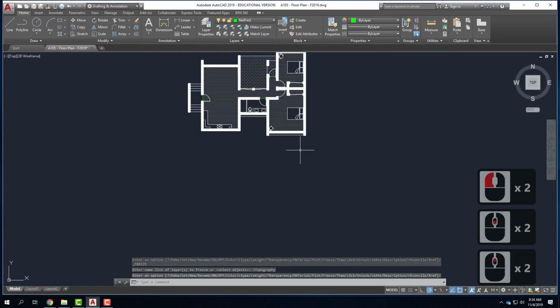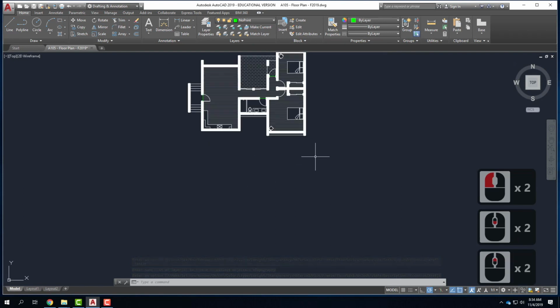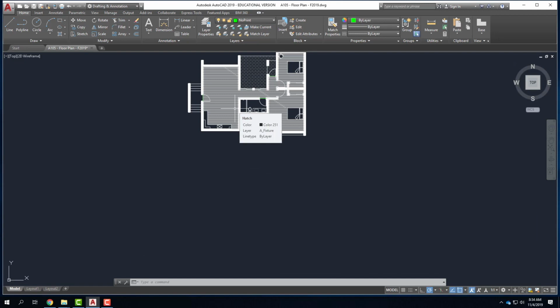There it is. We'll go ahead and turn that one off just so that it doesn't distract you while you're working on it. And I'm going to use my building's plan as a general guide as I lay out this particular building. So I need some guidelines or construction lines that I would pull down from the corners of this building, there, and there, to give myself an idea of what the shape of the building would look like. There are two types of guidelines that are available to you in AutoCAD. One is a construction line.